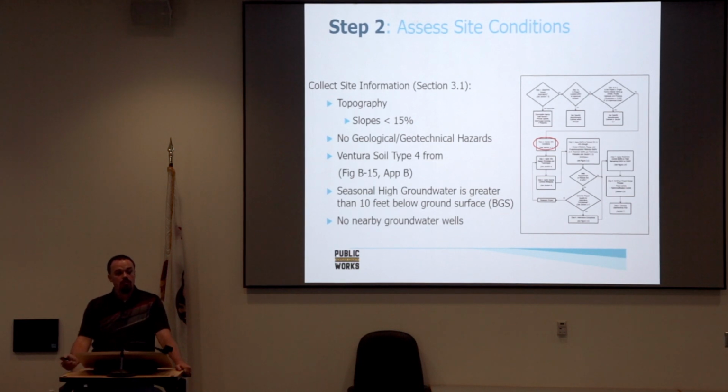The way we do it is with the LiDAR contours that we discussed in the first session. You can just overlay them over your site to see what the existing surface is. In this case, it's a redevelopment, so it's all going to be fairly flat. It's already a constructed parking lot. But if it's an undeveloped site, it's fairly easy to identify. You can even use Google Earth now. You can do sections in Google Earth, and it'll give you general profiles for the elevations.